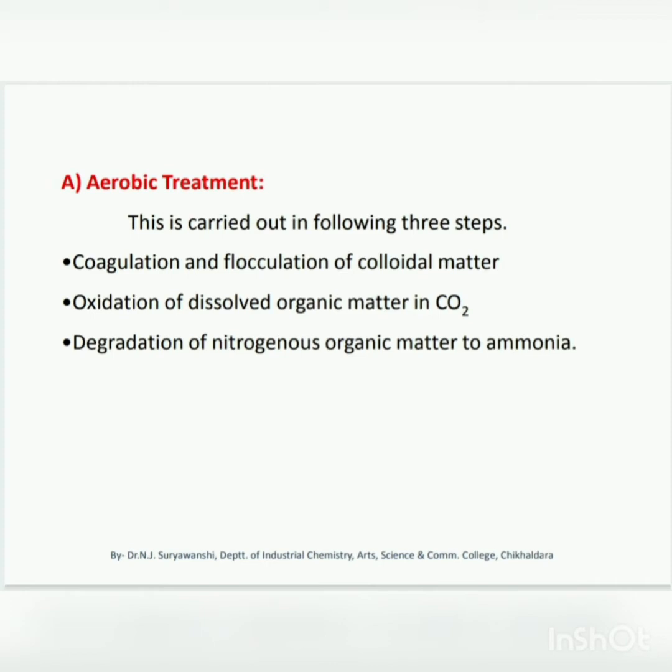First, coagulation and flocculation of colloidal matter. Second, oxidation of dissolved organic matter into carbon dioxide. Third, degradation of nitrogenous organic matter to ammonia. Almost all organic substances, with a few exceptions like hydrocarbons and ethers, can be oxidized by aerobic biological treatment. Thus, secondary treatment reduces BOD.